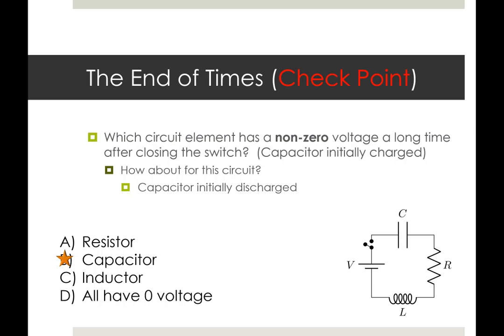Okay, this time the capacitor winds up with a non-zero voltage, but everything else has 0 voltage on it other than, of course, the battery. Because the conceptual behavior here is we try to charge the capacitor, but we overshoot, and we keep bouncing on either side of overcharged, undercharged, overcharged, undercharged. And then the resistor squeezes us in over time to equilibrium. But once we've reached equilibrium, there's no more current, and we're at steady current, and we're fully charged. So 0, 0, full voltage.